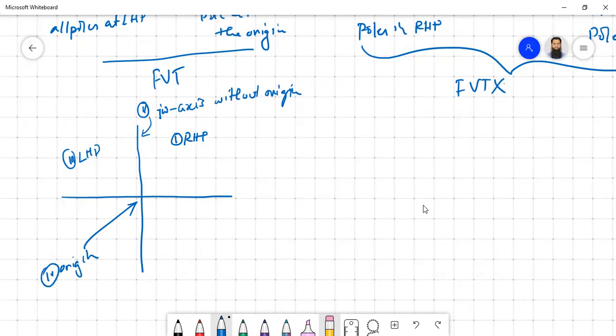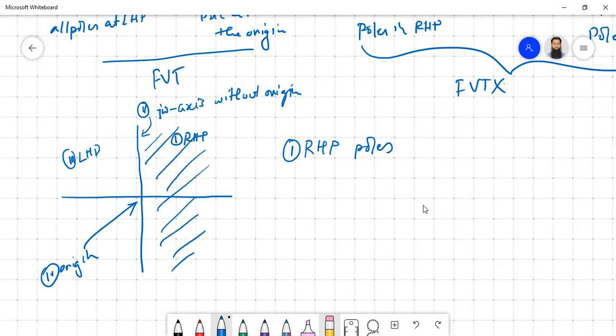So now let us look at the mathematical analysis, which one gives the correct result and which one gives a false result. Say first, right half plane poles, in this zone basically. In this zone, the system will definitely be unstable, no question about it. And graphically, this will be the case scenario, because you have some e to the power plus some value, some real number maybe.